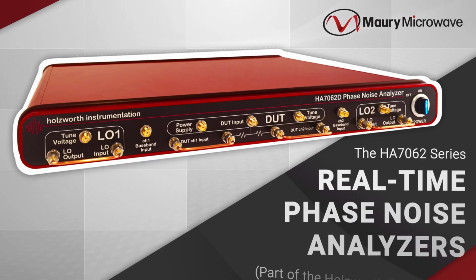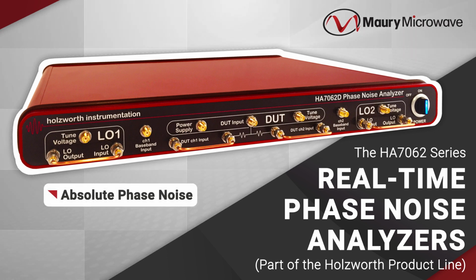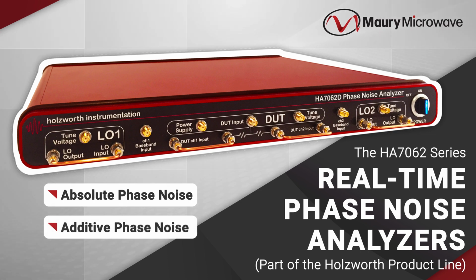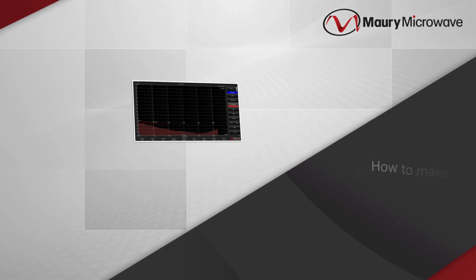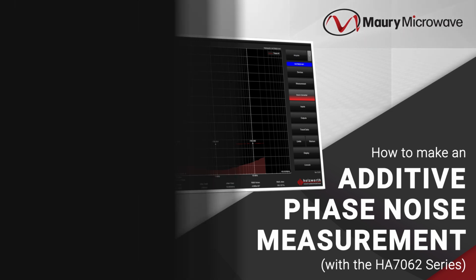HA7062C and HA7062D phase noise analyzers are able to perform a number of different measurements, which allow engineers to measure the phase noise of the entire system with an absolute measurement, or from one component of the system with an additive measurement. Today I'll be covering how to measure the phase noise from an individual component of the system that does not natively create an RF signal.